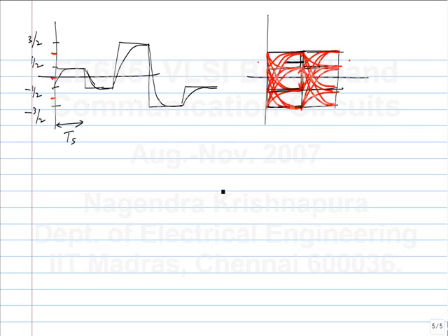So it can look more and more attractive as you increase the number of symbols. So this is the eye diagram. It's very easy to generate. Once you learn how to interpret it, it's also very useful. And this is the standard way of specifying the quality of the received signal. It's pretty clear because the eye diagram itself is periodic, very intuitive and easy to look at. If I just look at the signal, then I have to see what pattern it is and whether this is really the worst case or not. If I look at the eye diagram, I already know what the worst case is, worst case of intersymbol interference or jitter.